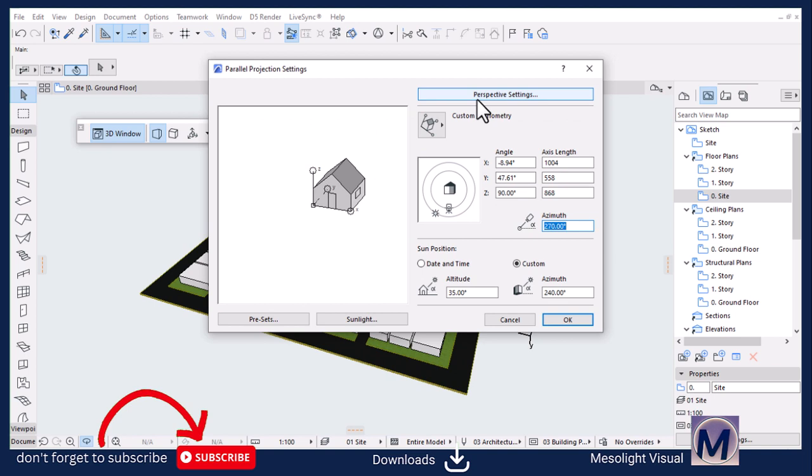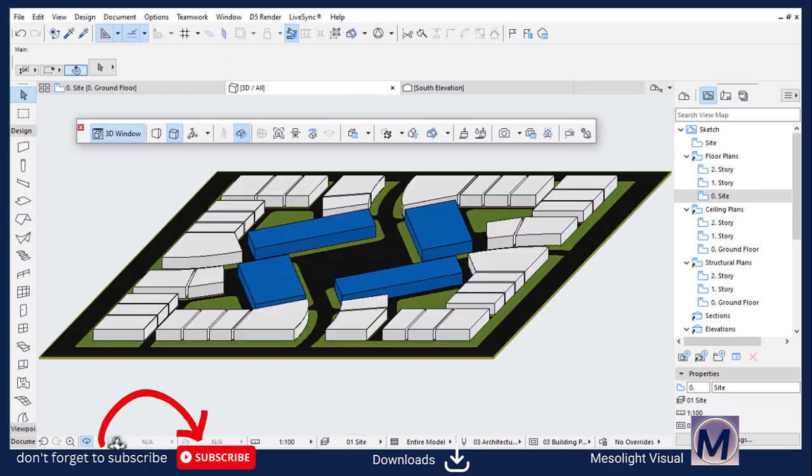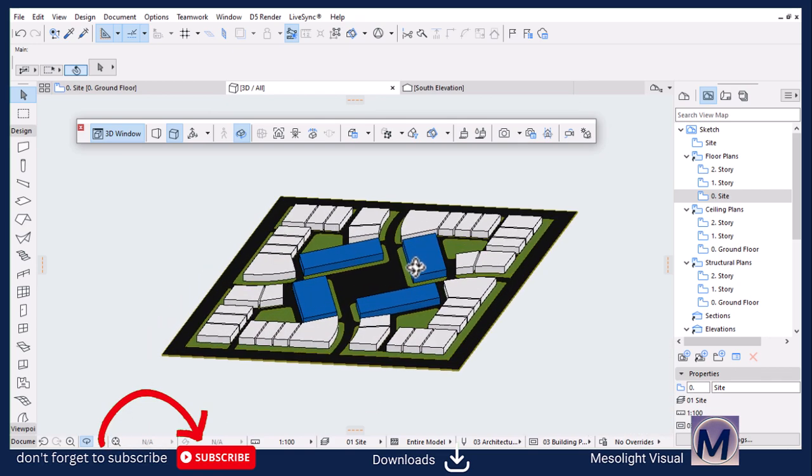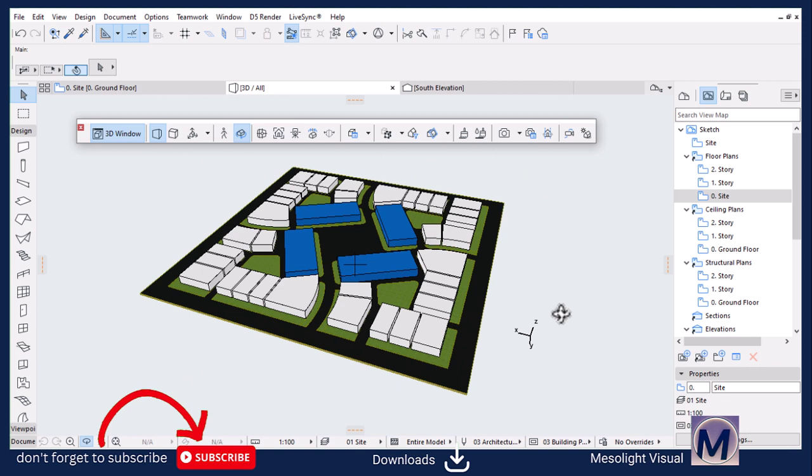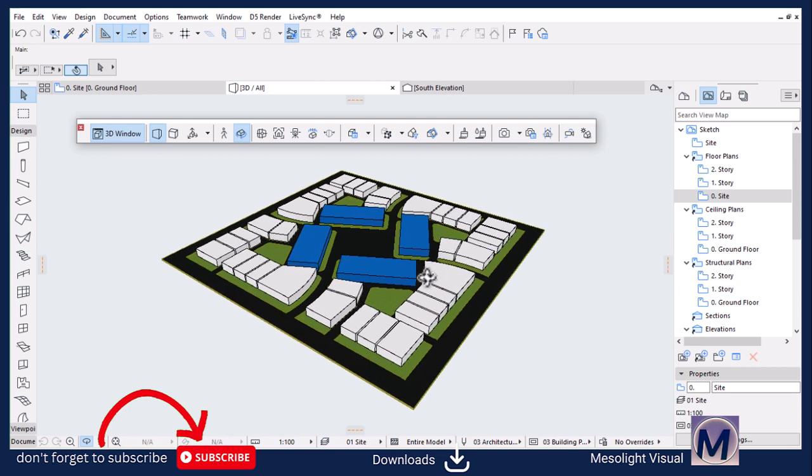Let's find something like this. Okay, we can define our custom settings here. So let's say we want the X to be straight, the X-axis. I'm going to set it to 0, and then this I'm going to set to 45, which is the Y. Let's hit OK, and then fit in the window. It doesn't look right. Let's go back here. Yes, perfect. This is what we want. So I'm going to right click this, but I need to see it also in this direction. I'll rotate it a bit like that.